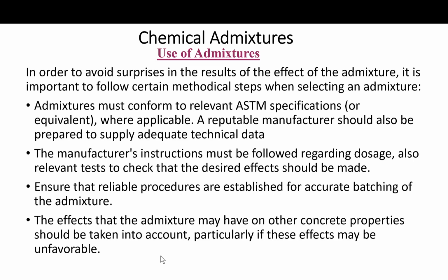For example, the air entraining admixtures should conform to ASTM C260, which is essentially a performance specification in which the admixture is tested according to the provisions of ASTM C233. Now, how to know the effect of this admixture is fit for purpose? There is a key test in this method, which is the performance of concrete exposed to rapid freezing and thawing according to ASTM C666.